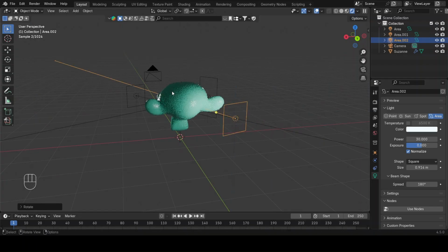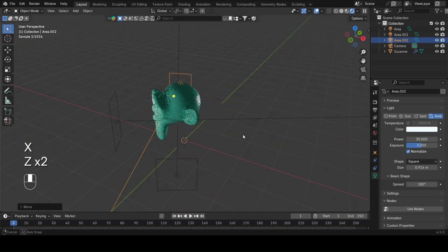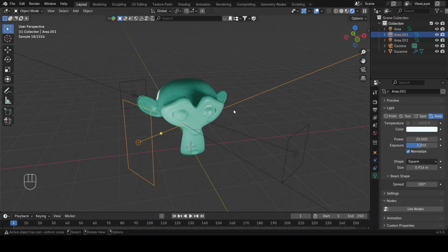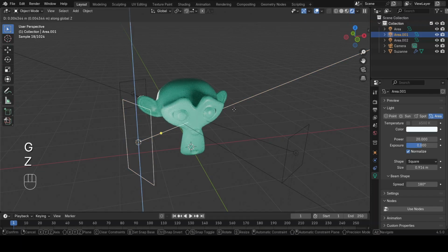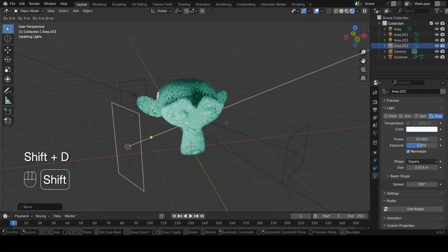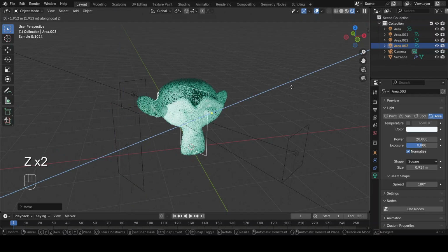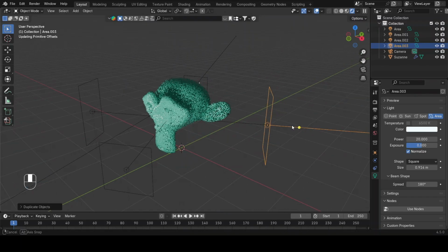like this. And then if you press G, or the grab tool, on your keyboard, like G and Z, your object will move on the Z axis. But if you press Z again, then your object's direction of movement will be different. But before this, let me duplicate this and then press Z once and again to change the view of it, to give it a light.